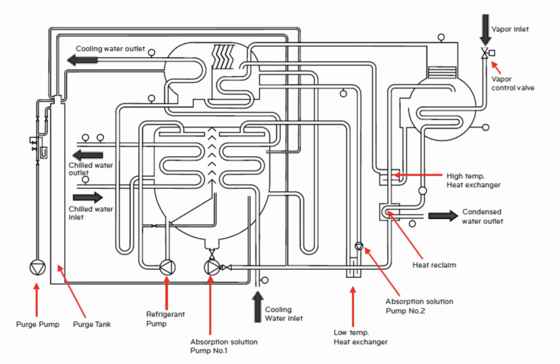Vaporized refrigerant from the high-temperature regenerator flows into the heat transfer tubes in the low-temperature regenerator. At this time it works as the heat source, heating the absorption solution, which is intermediate solution. Vaporized refrigerant, which has passed the low-temperature regenerator, heats absorption solution and is condensed into liquid.